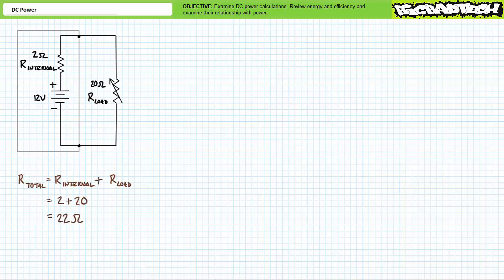The 12-volt source sees the series combination of the 2 ohm internal resistance and the 20 ohm electrical load for a total resistance of 22 ohms. Total resistance went down. Current is equal to voltage divided by resistance. Ohm's law demonstrates the source would provide roughly 545.5 milliamperes of current. Given total resistance went down, it is entirely understandable current went up.